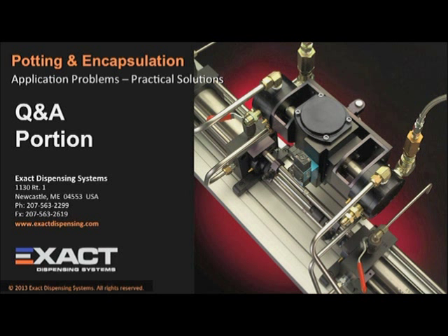We would normally try a tilted dry assembly, a few degrees, let's say 5 or so degrees on one corner, and position the tip of the dispenser below the highest corner an inch or so, or a third of the way towards the center, and then let the liquid flow.